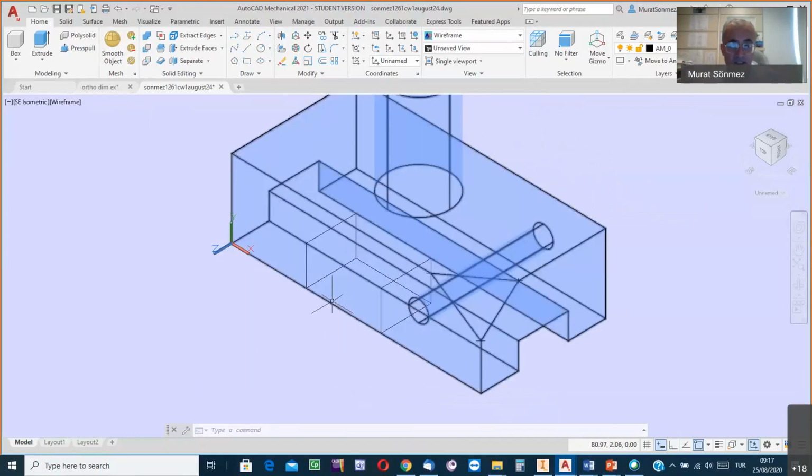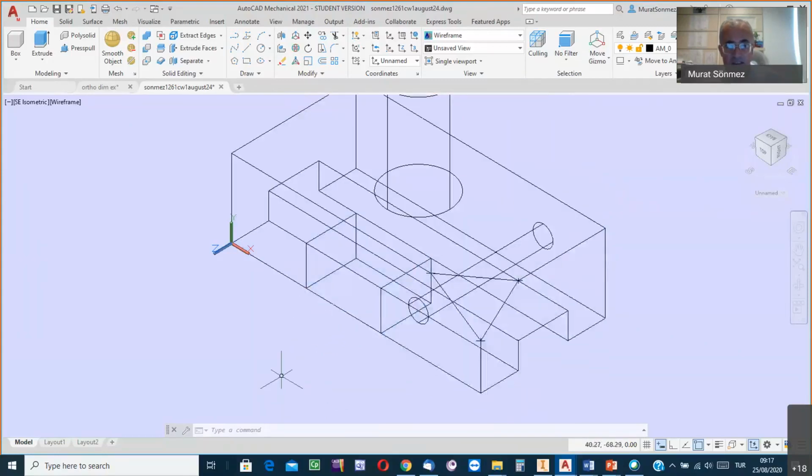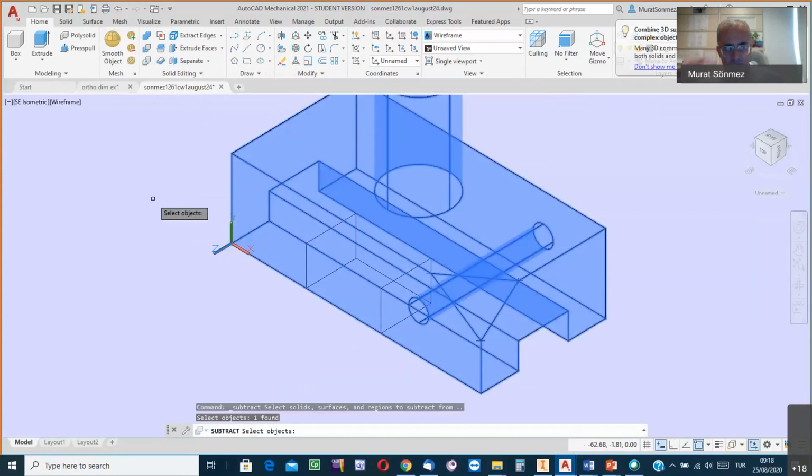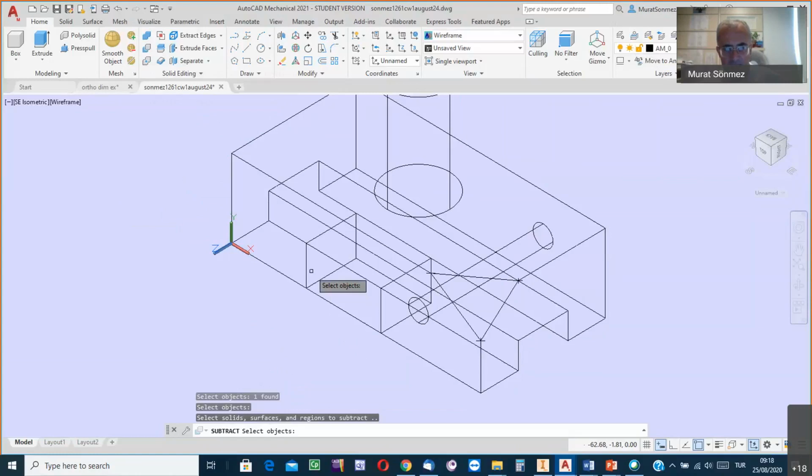But it is not the end of that creation stage, because in AutoCAD I now have a solid rectangular prism within another solid rectangular prism, as if it were an assembly. I need to apply the subtraction process at this stage. Click on the subtraction button, and first indicate the main part to subtract from. Don't forget to click the enter key. Then subtract the newly created one, indicate the second box, and press enter. Now it is an empty space.